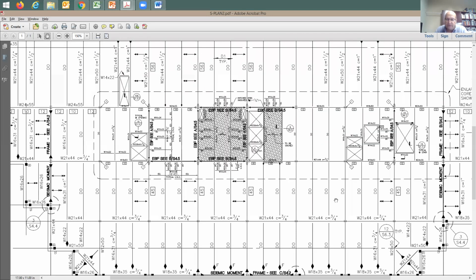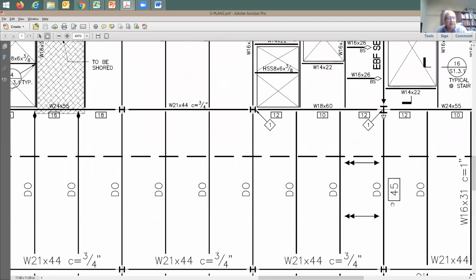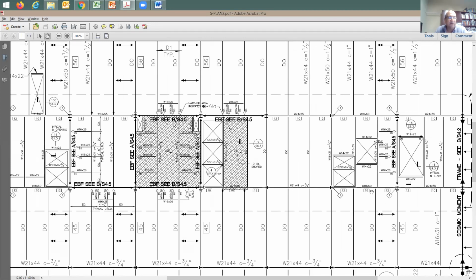The standard that we're doing here is that we're going to be providing a stud per foot, just one stud per foot, unless we come here and put the number of studs in a box like this, which means I need to add 45 studs from that point to this point. Otherwise, it's going to be 1 per foot, meaning from here to here, I have 3 studs. But in here I have 45.